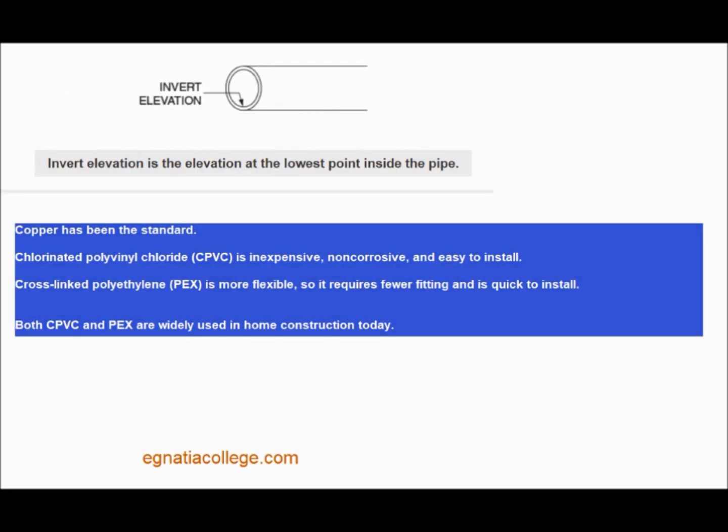The design of septic systems is closely regulated by most health and plumbing codes. These local codes should be checked before designing or installing any septic system. The building code or health department code often requires a percolation test before the system can be approved.